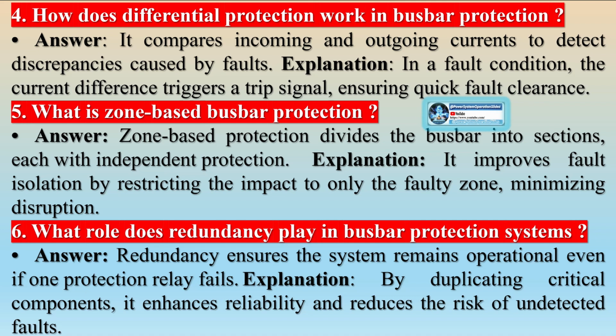The scheme's output can result in different actions: a retrip function, a backup trip function, and inter-tripping. It uses input CT, wiring, relay input circuitry, and firmware to issue the trip command and determine if the breaker has failed. Multiple operational copies of the BF function can potentially compromise its security. Some multi-input relays mitigate this by allowing different CT, wiring, and relay inputs for the BF function.